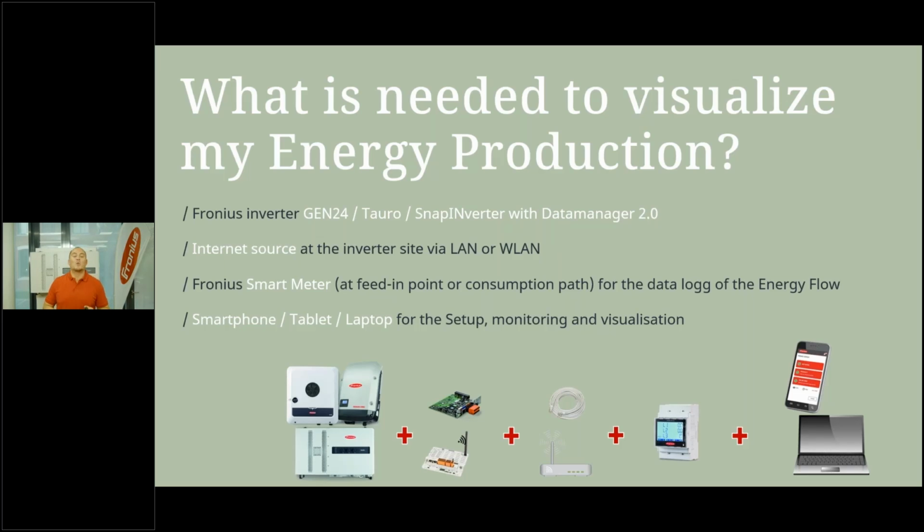I want to make an important note on the location of the smart meter. It is always recommended to install the smart meter directly at the feed-in point to the grid. In this way, power flow from the grid and to the grid can be recorded, acknowledging how energy flows happen at this point. To close the explanation, once your system is active on the Solar.web app or platform, you can now visualize all mentioned values using your smartphone or your laptop.